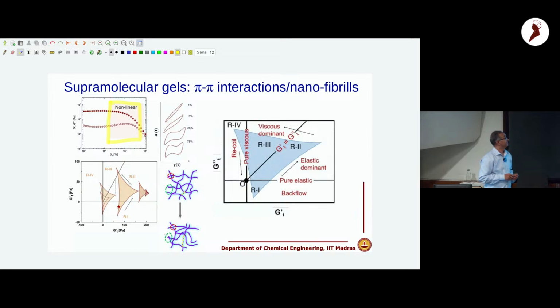So this starts well before the yielding, right? What starts? I'm saying the nonlinearity starts probably much earlier than what is indicated here. Perceptible, yeah, absolutely. So looking at just this and saying it's constant may not be really correct. It could be much earlier than that. Only worm-like micelle is a perfectly elastic system to very, very large deformations, but most other systems start showing a significant amount of nonlinearity, sometimes not well represented by the first harmonic.